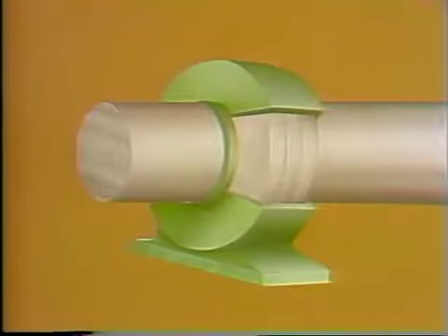Now keep this in mind as we describe how the bearing works. When the shaft tries to move, the rotating ring pushes against the rolling elements, and the rolling elements push against the stationary ring. Since the stationary ring is attached to the housing, axial movement is prevented. This type of bearing prevents axial movement in this direction only. We've now seen how rolling contact bearings and sliding surface bearings perform two of their three basic functions: supporting loads and preventing undesirable movement. Now, all along, we've indicated that bearing parts don't actually touch.